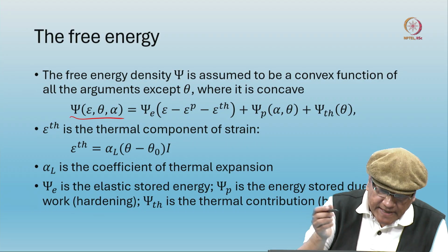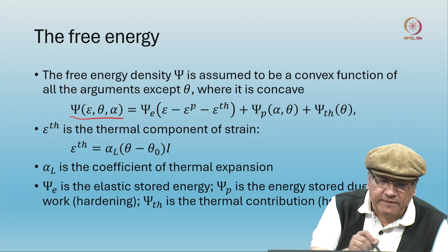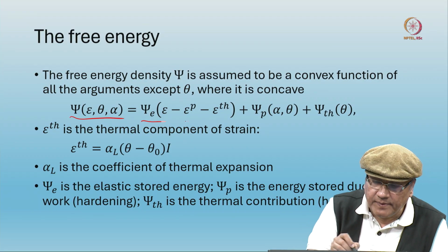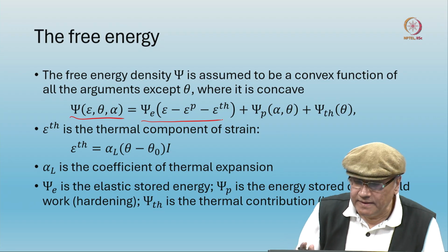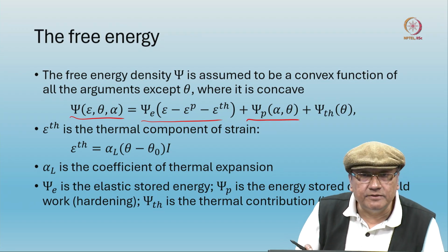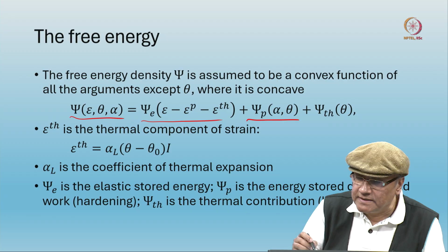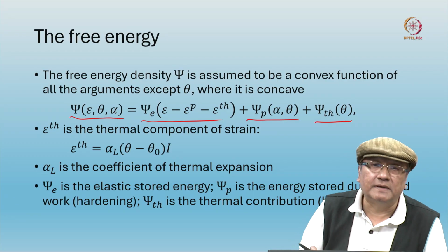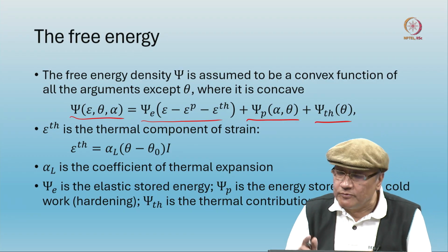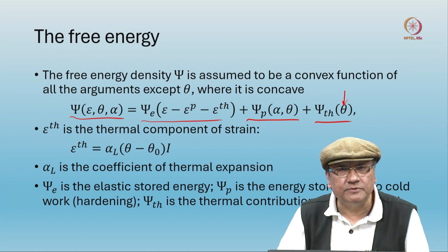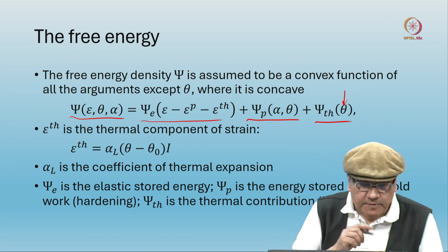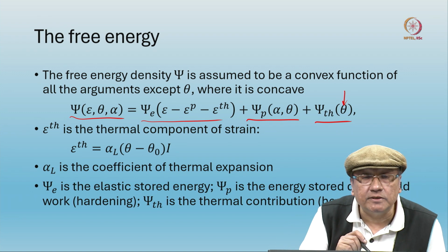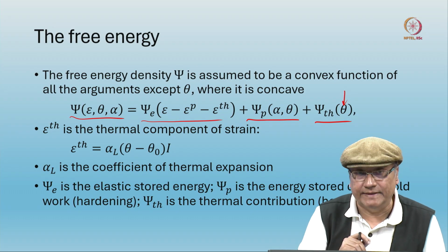So, here we do the same thing. So, in this additive decomposition of the free energy, one part is the purely elastic part, the second part is due to the plastic flow, okay. The third part is because of the thermal part, that is due to heat transfer, which is a function of only the absolute temperature. The first part is obviously a function of the elastic strain.